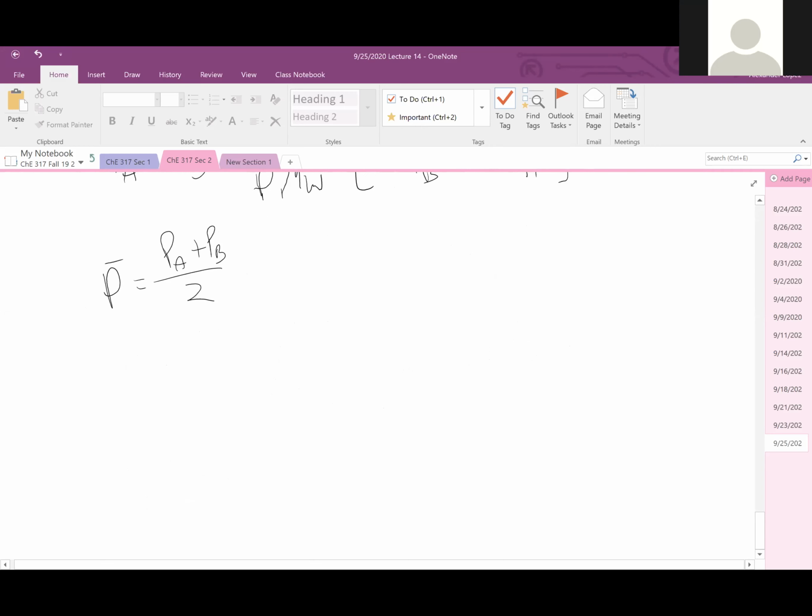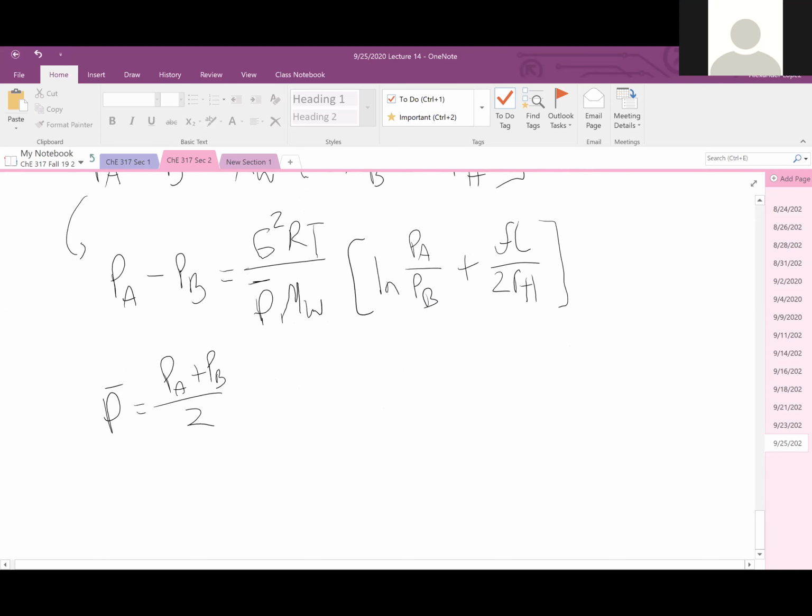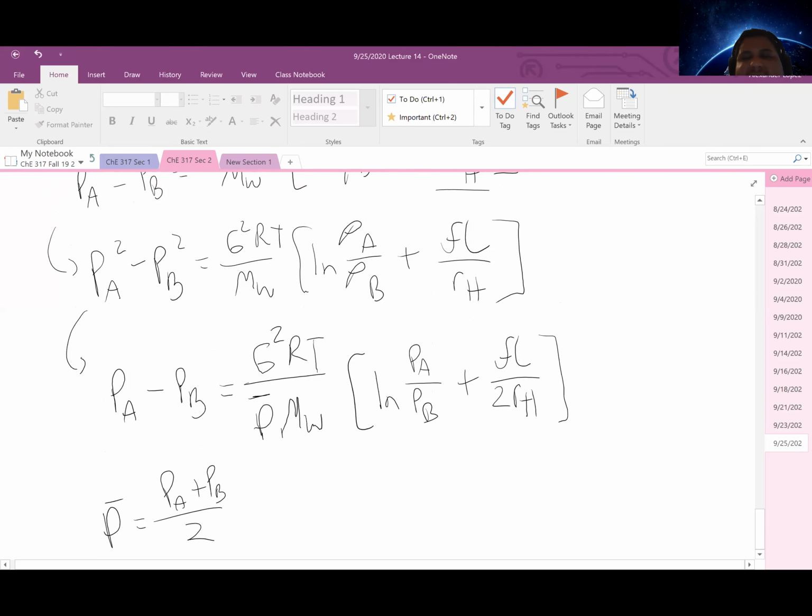So the friction factor in these equations is not the average one that we looked at with adiabatic. That's a good question. It is and it isn't, typically, because when we were looking at friction factor, we use Reynolds number and K over D to solve for it. And when we're looking at Reynolds number, we have mass flux times diameter over viscosity. Now for isothermal frictional flow, the temperature is constant, which means mass flux is constant, diameter is constant, and viscosity is constant.